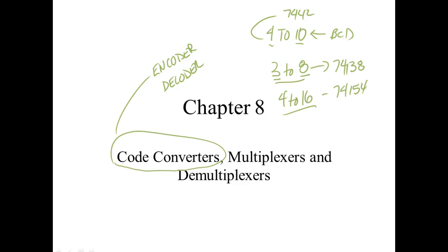So they maintained this spacing that y'all been dealing with up until they got up to 22 pins. Then when they got up to 24 pins, what they basically did, I guess you'd say it's double the size, is they went to a wider IC. This got us all the way up to 64 pins. This spacing or this size. So here's a 74154.